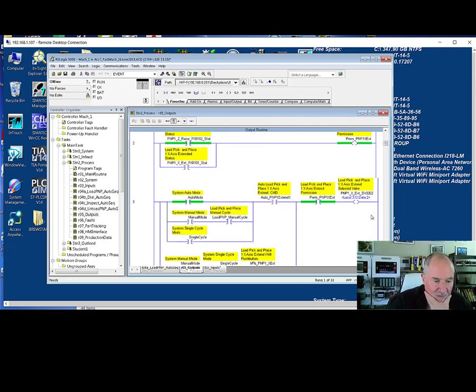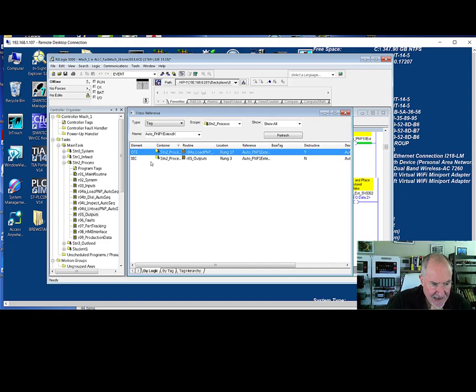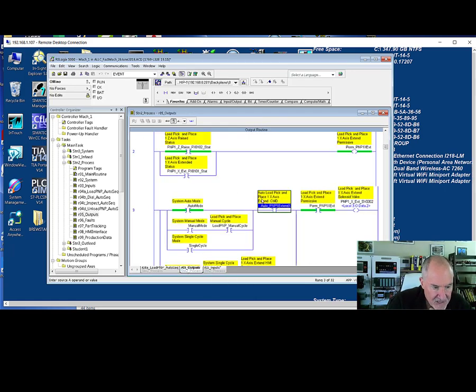In this case, we're going to pick something a little different. We're going to say the x-axis failed to extend. And the reason that it failed to extend, it looks like all the permissives are there. Everything's okay. I'm raised, but I did not get this command. So I'm going to once again go to the reference data for this and find the destructive bit. So this is a writable command, right? It's destructive. And so I'm going to go to it. Before I actually do that, I'm going to go back to these outputs and I'm going to bookmark this, right?